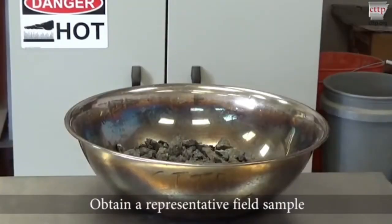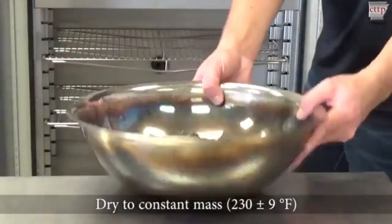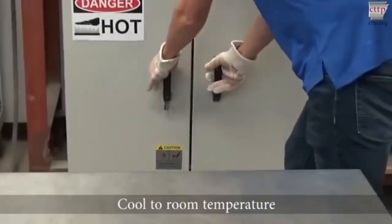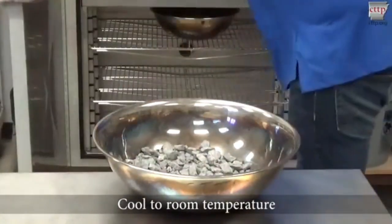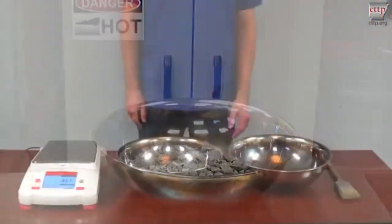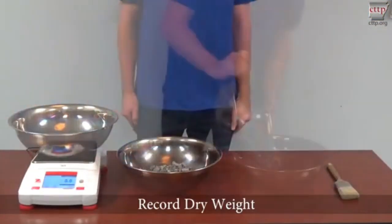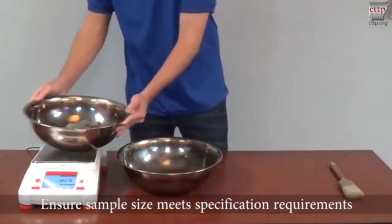Obtain a representative field sample of aggregate. Dry the sample to a constant mass at 230 plus or minus 9 degrees Fahrenheit. After drying, cool the sample to room temperature. Then record the dry weight. Ensure that the sample size meets specification requirements.